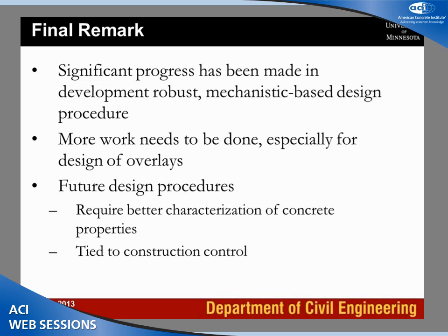Absolutely. Well, I'll repeat the question. The question is whether we need to make efforts on the construction process, not on the design process, because at that time it's too late. Absolutely, but to really improve our construction practices, we should have a better understanding of the effect of built-in curl, and develop procedures and understand the parameters which we must control during construction.